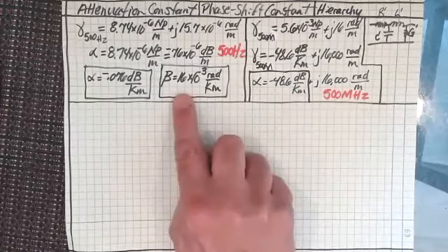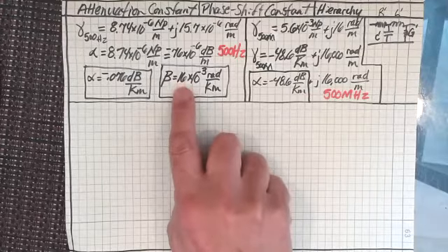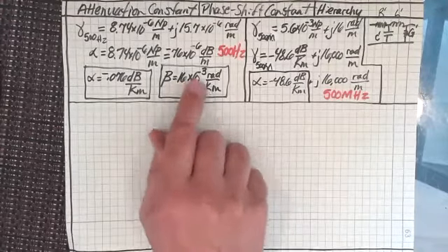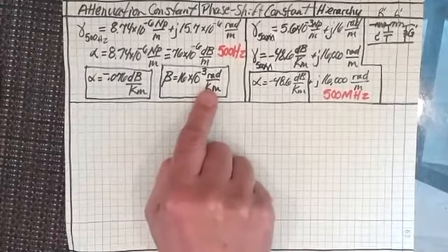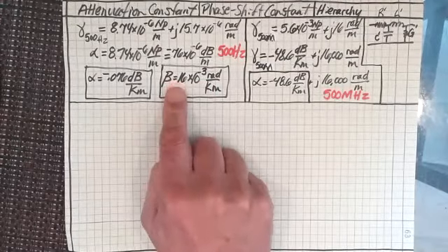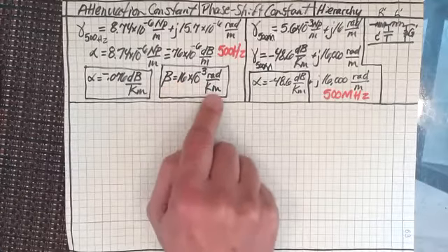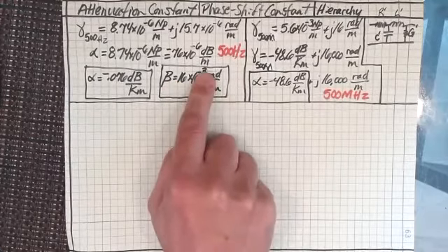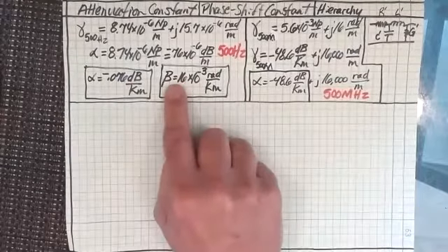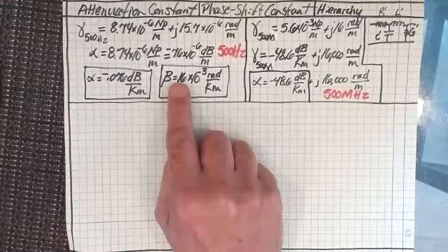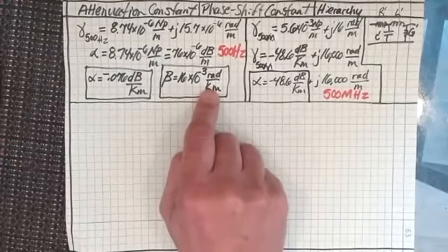Let's look at the phase shift, the phase shift loss, energy loss. So with a 500 hertz signal going 1,000 kilometers, I would only have 16 radians, right? Does everyone see that? 16 times 10 to the minus 3. So if I multiplied that by 1,000, that would get rid of this, and that would leave 16 radians for 1,000 kilometers.